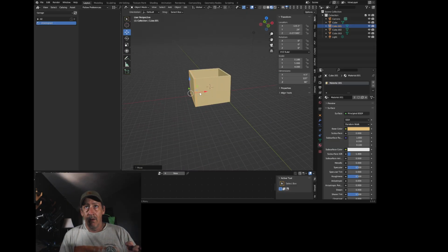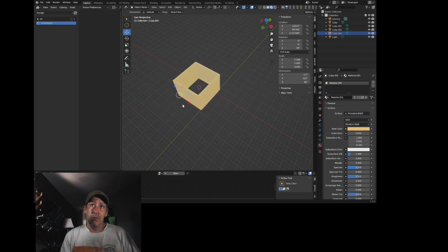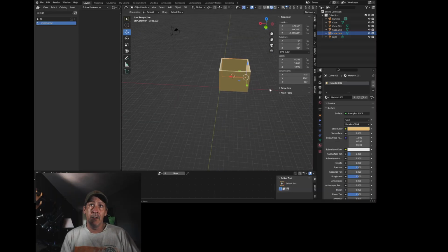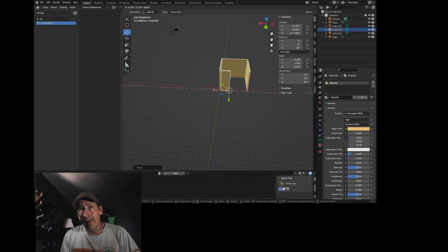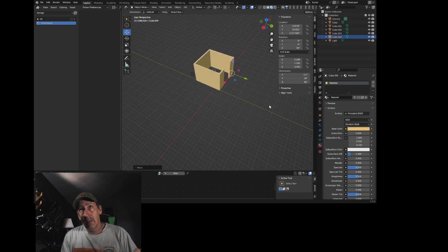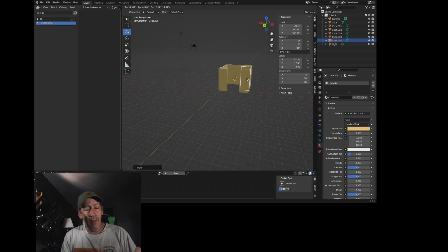But we basically made 4 walls. So we've got like a little room. And then you can add a door later, or maybe you don't want to have, maybe this is, let's see, 60 inches minus 24, 36. So if we do 36 inches over here and 36 inches over here, we've got a doorway. And then you can put a header over here, rotate Y 90.